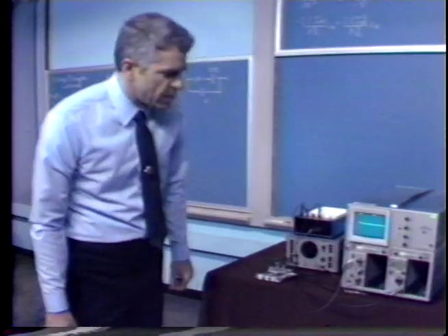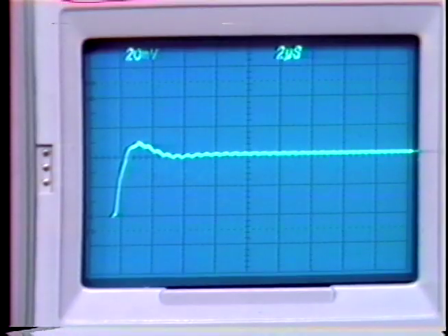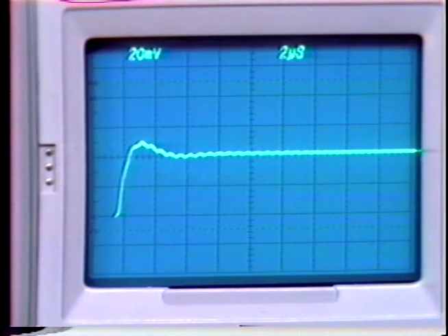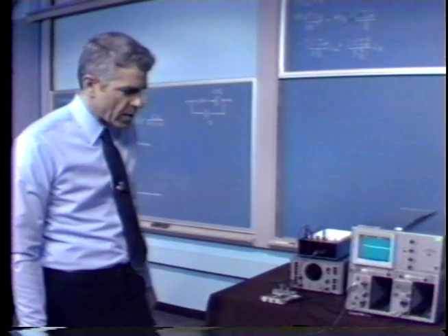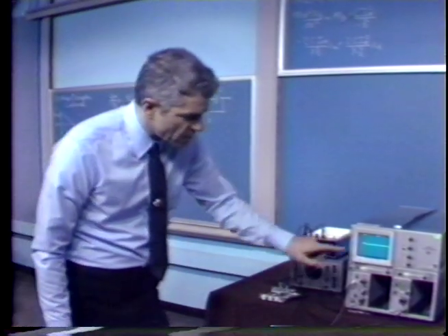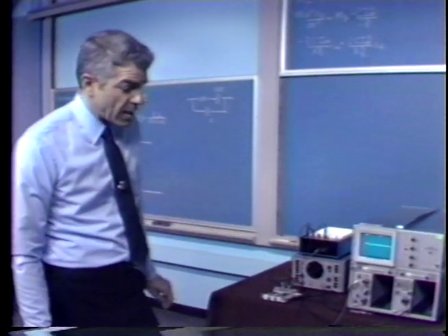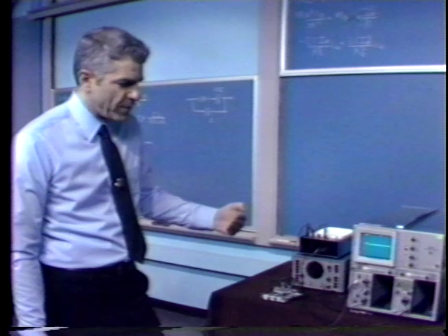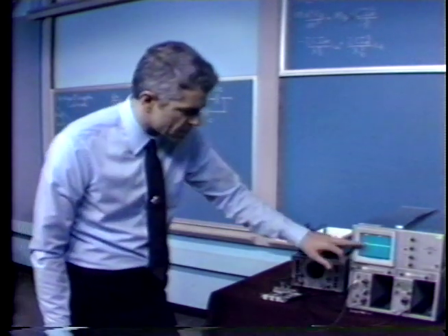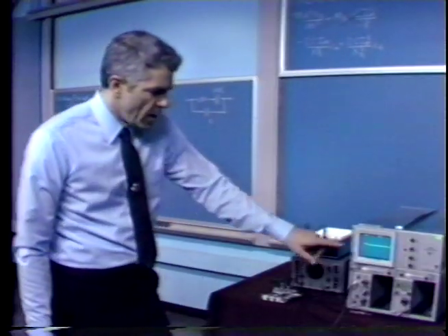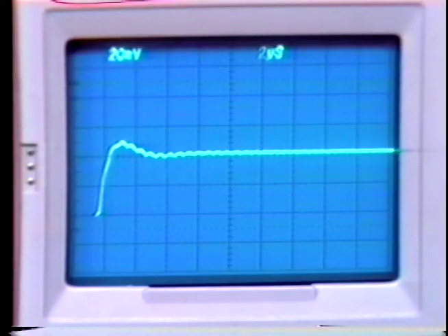The frequency of the teeth is several megahertz, and we're looking at that through a very low-pass filter because of the output resistance of the operational amplifier and the 1/10 microfarad capacitive load. And so we see just a little remnant of this large oscillation that's occurring at the actual output of the second stage before the final buffer amplifier associated with the op-amp. And there's some nonlinearity, there's some crossover problems and so forth. But I believe that the teeth reflect an impending minor loop instability.